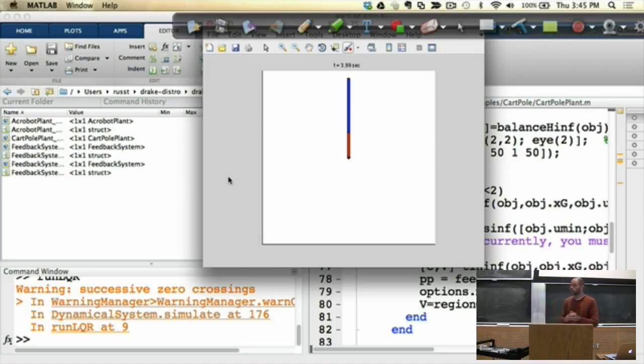Yeah. And do we have actuation limits in this framework? Good question. The LQR does not have actuation limits, but on Tuesday we're going to show you the way we do that in practice. Just to give you a hint, basically we'll solve the Riccati equation, the LQR problem, as if there were no actuator limits. And then when we actually go downhill, we'll take into account the actuator limits. So we'll go downhill as best as we can given the actuator limits, but still pretend that after that I would have had infinite, or whatever, torque I needed. And that turns out to be a powerful thing that we can do even on humanoids, for instance, okay?